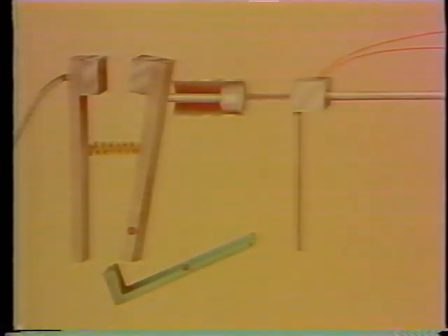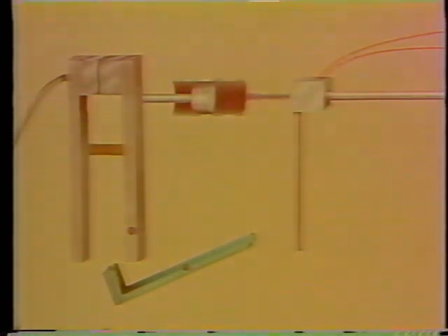Circuit breakers can also be closed from remote locations. We're going to look at three methods that are commonly used to close circuit breakers. First, we'll see a piston operated by air pressure, then a spring, and finally a solenoid. Air pressure closes the contacts in this circuit breaker. When you turn the right switch on the control panel, it opens a solenoid valve to feed air pressure into the cylinder to push on the piston. The piston moves and the contacts close.